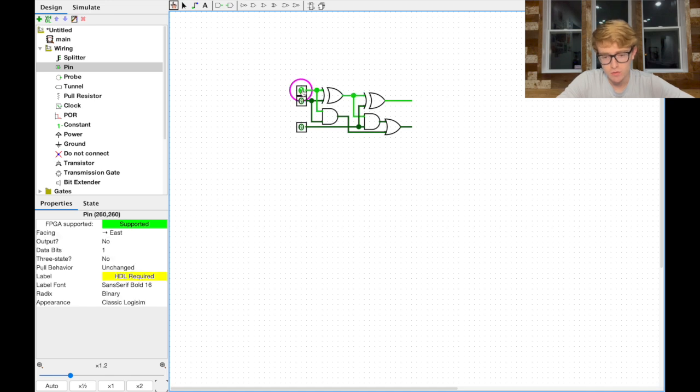And I can sort of simulate how this works. So we can add 1 plus 1, same deal as with the half adder. It gives us a sum of 0 and a carry of 1. 1 plus 1 plus 1, so if Cn is 1, then we get a sum of 1 and a carry out of 1. So you can see we can go through and actually simulate what's going on.